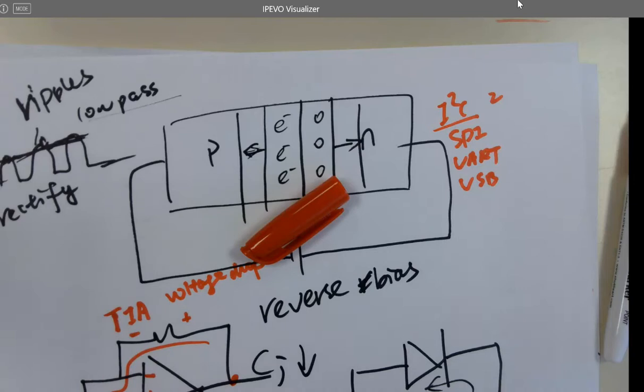And then followed by the address. The digital device has the memory, all the different addresses, and follow the address. I want to take data from some address here. It's an 8-bit address, FA or something. It's a hex number in there, and then start sending it, following the clock.